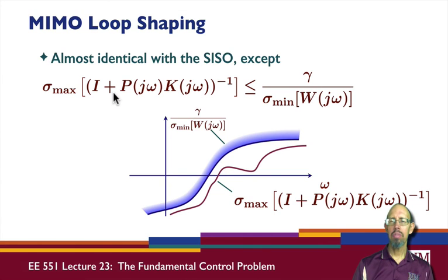and so again, in terms of a design process, given a P, we would want to find a K such that this inequality is satisfied, where W is given by the disturbance. And if it is satisfied, then our system will have disturbance attenuation and so forth. Okay, so now again, we not only want K to satisfy this inequality, but we also want K to stabilize the system.